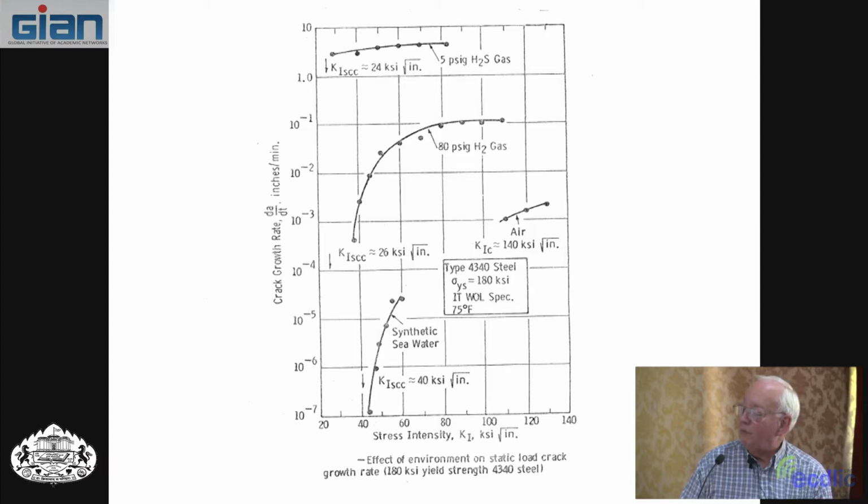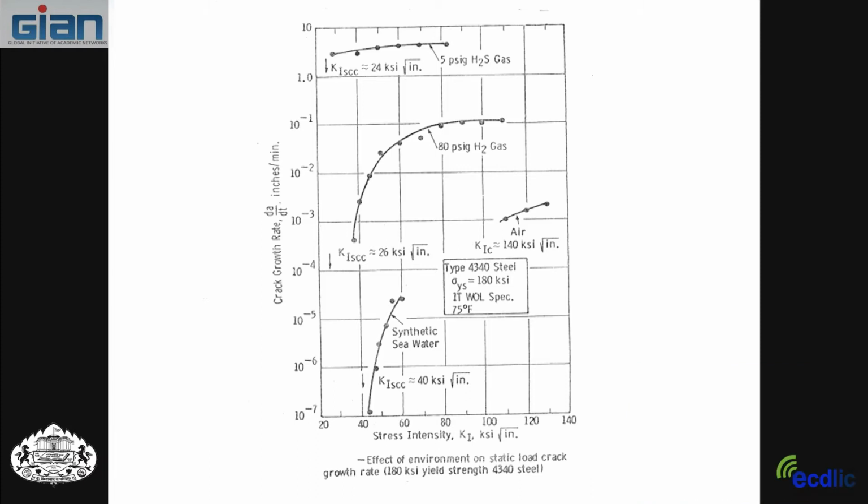So what happens is it develops multiple cracks. One of the things about environmental cracking is you often see multiple cracks, and they call that crack branching. So you have a main crack growing, and then all of a sudden, cracks start going out from that main crack. I have it here. I didn't get it in the right thing.